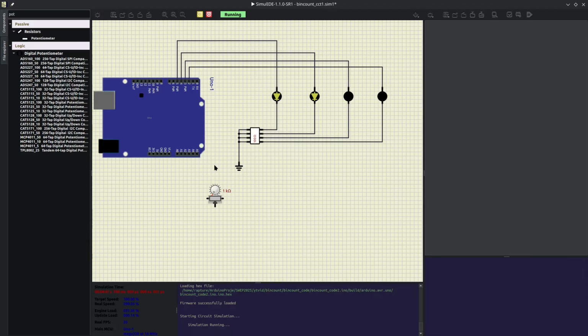To be able to get each value at a time, we're going to attach it to the analog section of the Arduino Uno. A0, A1, A2, A3, A4, A5 is where we are going to attach. We have 3 terminals in our port. The first one can be 0, or VCC, or the GND.